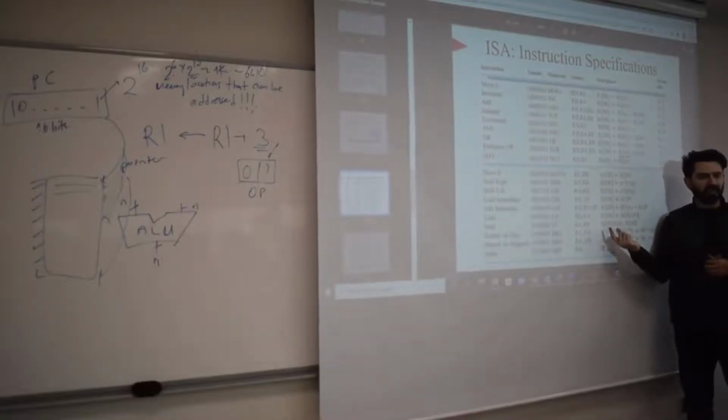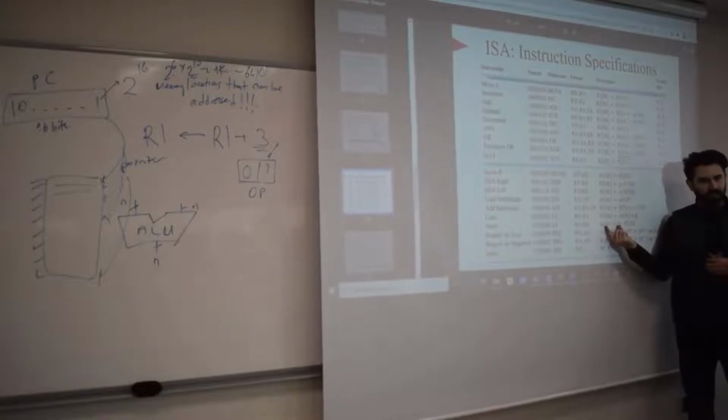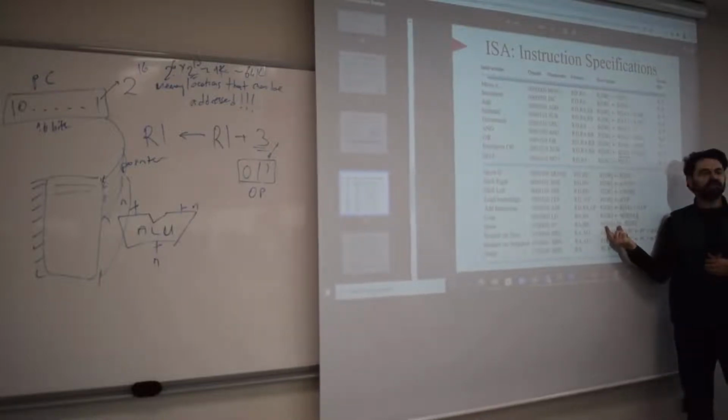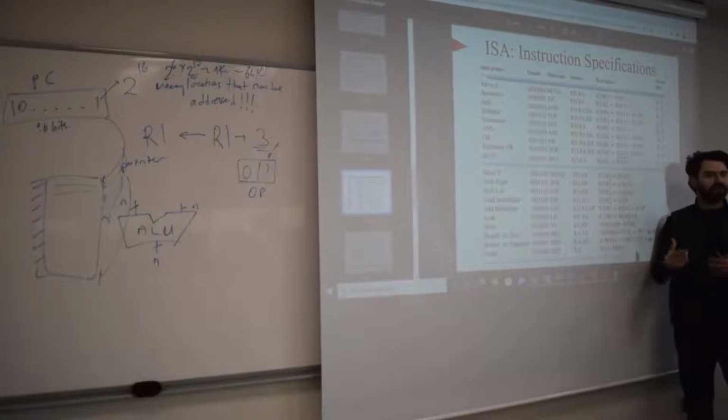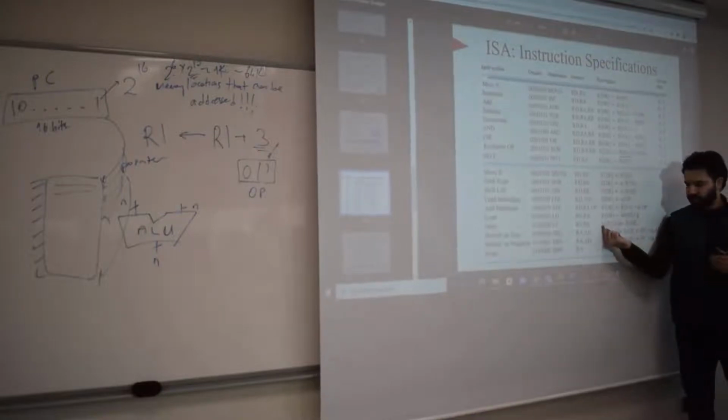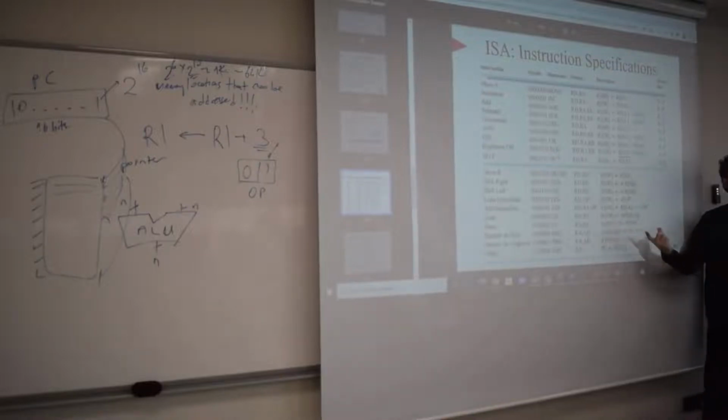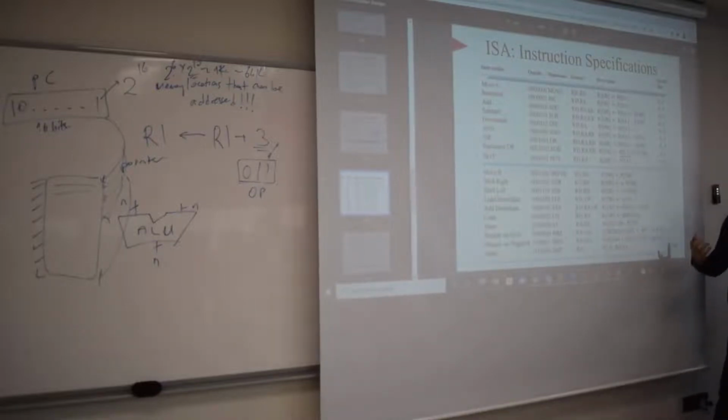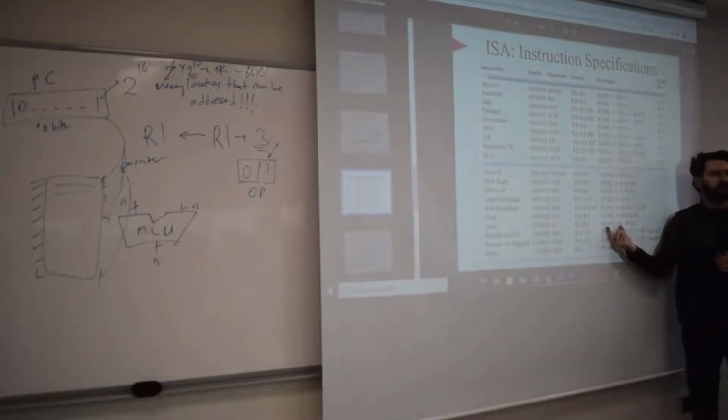The memory size is bound to be determined by the register size. Because if the register size is 16-bit long, then you can actually address 2 to the 16 memory locations, right? That also is an important observation here, although it's very implicit, but that actually tells us that the memory size is constrained by the register size.